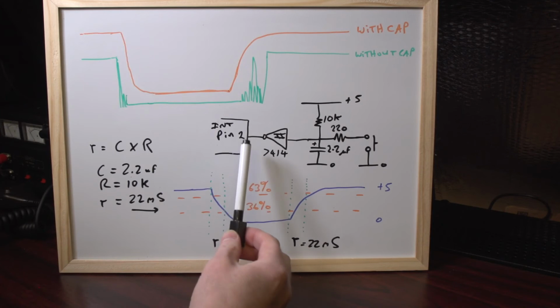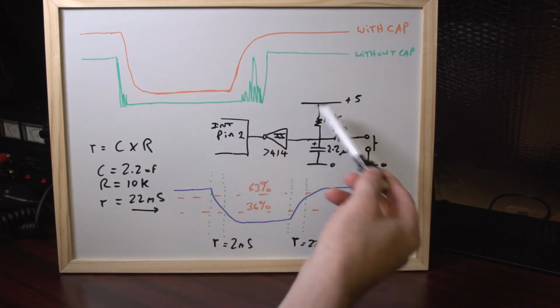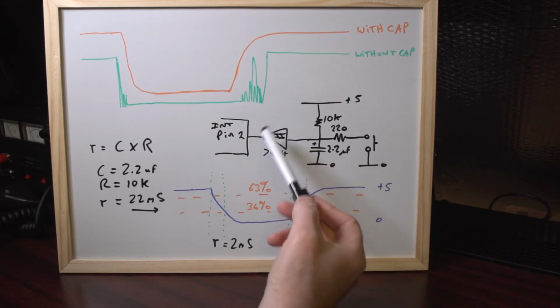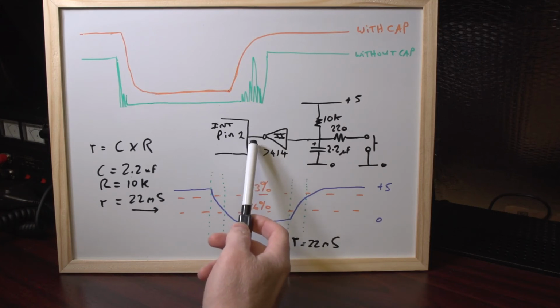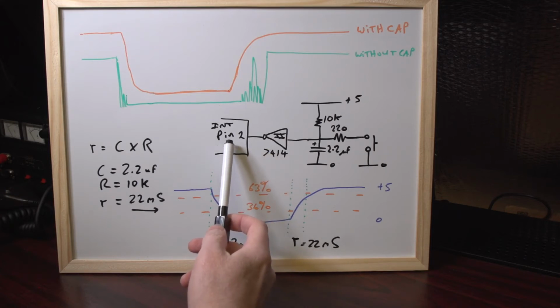That is then completely clean. You have no noise. It's been filtered with an RC circuit for contact bounce, and it's also filtered because we're taking out any noise that could be on the signal. It's giving us a very fast rise and fall time, typically 20 or 30 nanoseconds. So it's a very fast reacting output, and that's perfect for driving the interrupt pin.